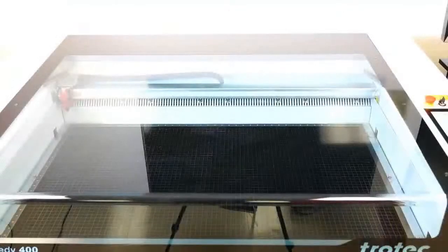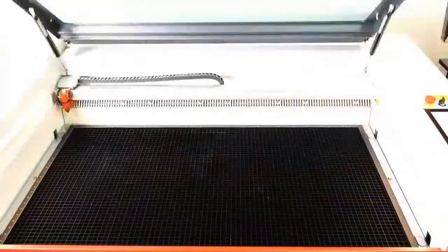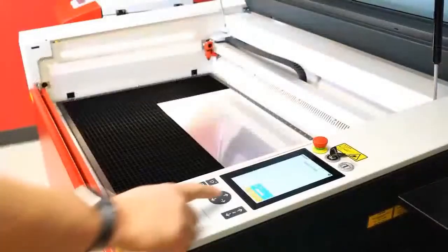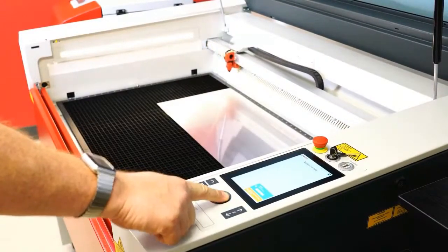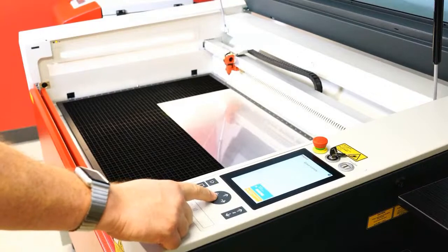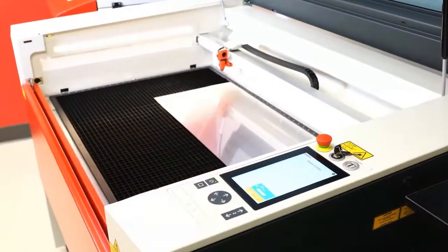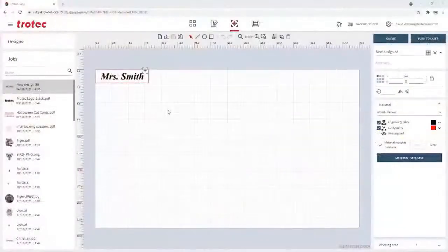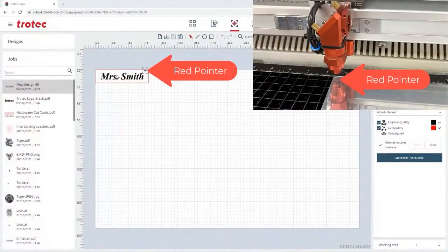This is how simple it is to run. We'll then go to the laser system, placing our raw sheet stock material. In this case, it's plastic with basically a metallic looking surface and a black core. So the laser will etch away through. I'll bring the head over the top of the material, press the focus button. Sonar will find the height of the material and focus for us.